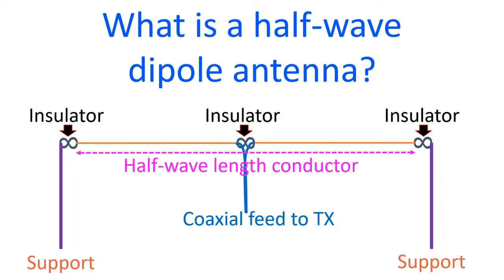Half-wave dipole antenna fed at the center is the commonest type of dipole antenna, and its length is almost half of the wavelength of the frequency for which it is meant. So the total length of a half-wave dipole antenna for the 40-meter amateur radio band will be almost 20 meters. The space needed for the antenna increases as you go down along the amateur radio bands. I had the opportunity to use both 40-meter and 80-meter half-wave dipole antennas earlier, but I'll have to struggle to get even a 20-meter half-wave dipole antenna up at my current location.